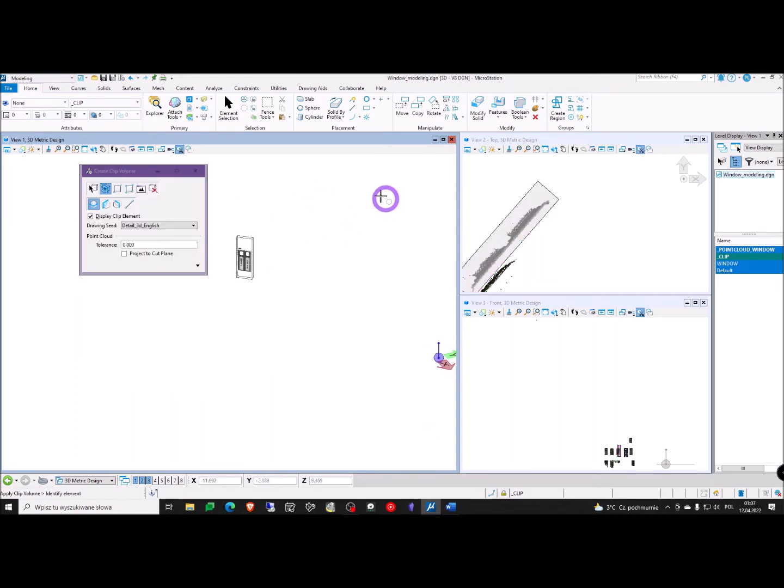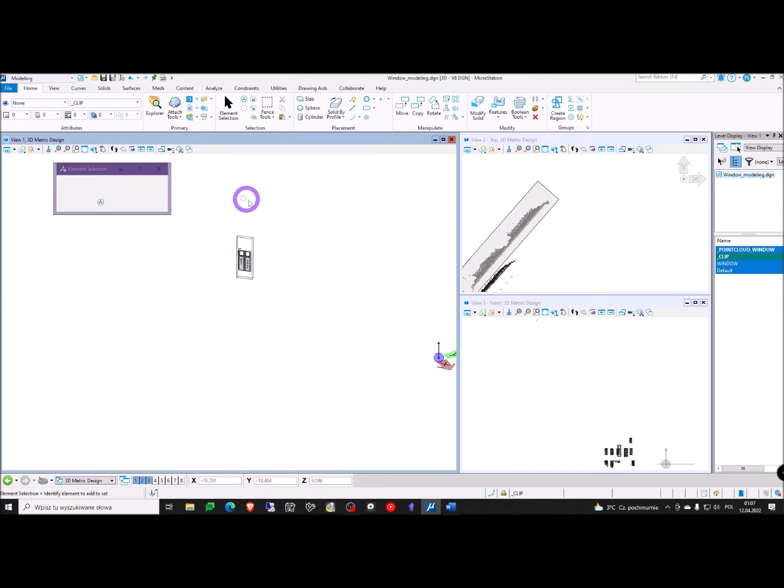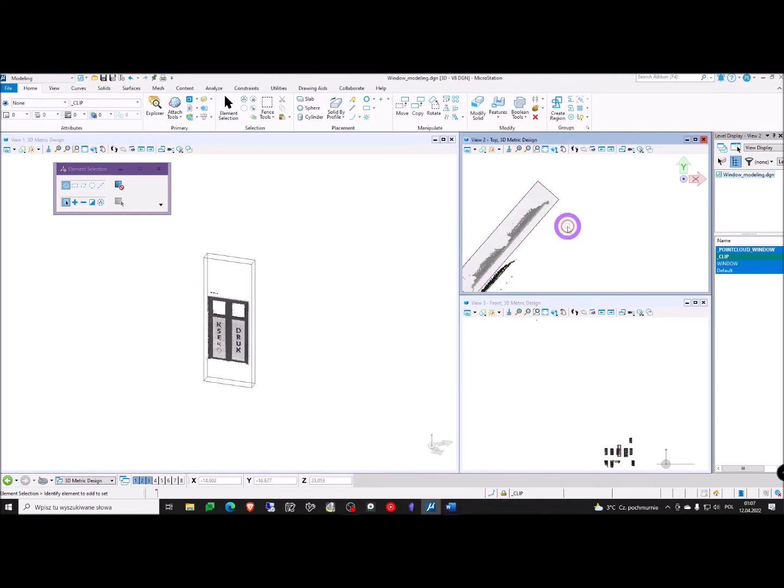As you can see, everything else in this particular view will be hidden, because we can only see in the limit of this box. In other views, this is not the case. We can still see every other element, because for one view we can only have one clip, and one clip can only be attached to one view, so it is one-to-one.